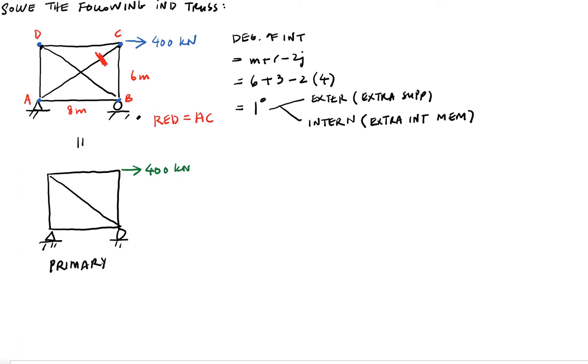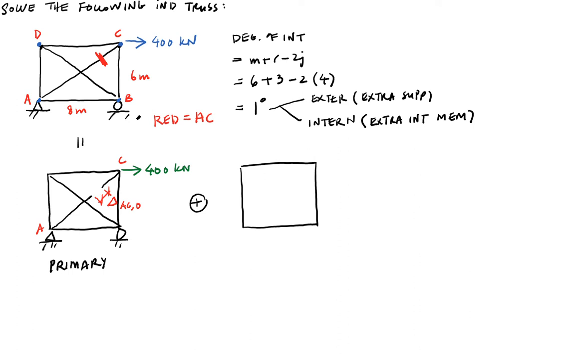Okay, so when you have cut your member AC, when you load it, member AC cannot take any internal force. Okay, and if there is a member AC that has been cut, what happens is under this load, it is going to be separated. There will be a separation of distance between the cut points, and let's call this distance delta AC 0. Okay, system number 0.